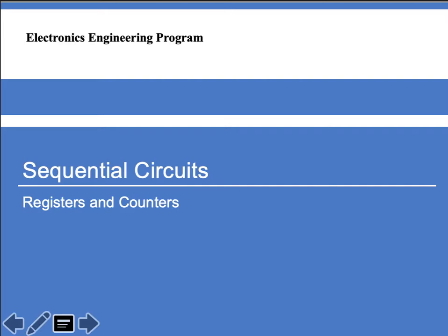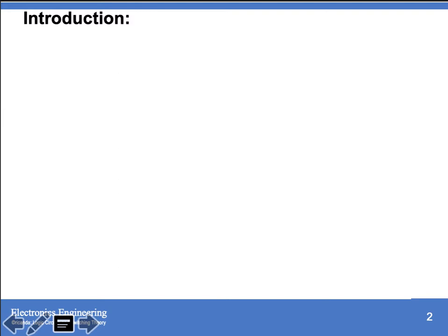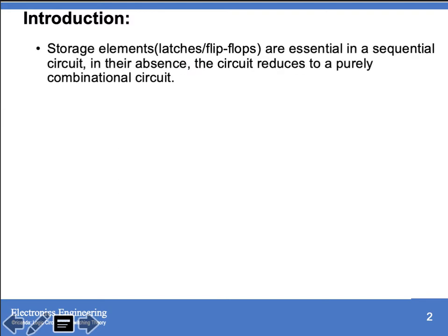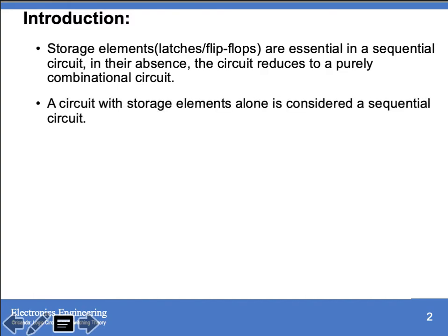Under sequential circuits are registers and counters. Storage elements, that is latches and flip-flops, are an essential part of sequential circuits. A sequential circuit without storage elements reduces to a purely combinational circuit. A circuit with storage elements is considered a sequential circuit.